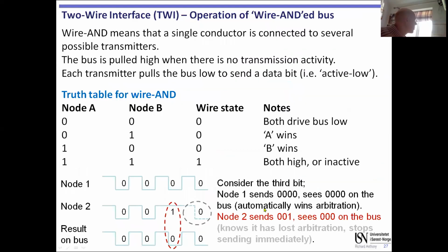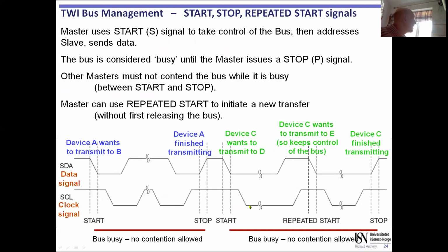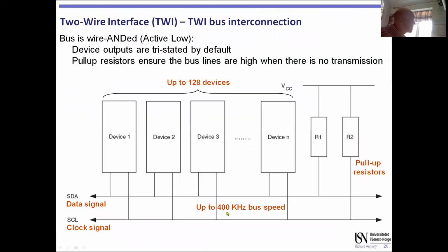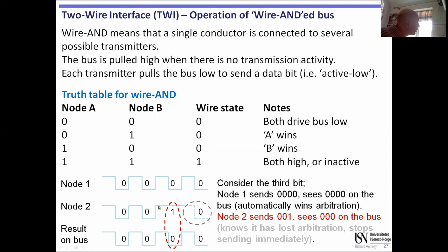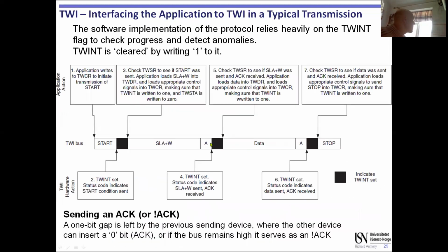Let's go back to that diagram of the wire. The master will leave the wire high. Oh, sorry, that's a better diagram. The master will leave the wire high on purpose, and the slave will send a 0 to say, I understand, I received that message. So the master purposely leaves the signal high for 1 bit and sees if the slave sends a low, like that. And that's what is happening here. And if the slave sends a low there, it means it understood that and it is ready to receive data. And then the master can send the data.